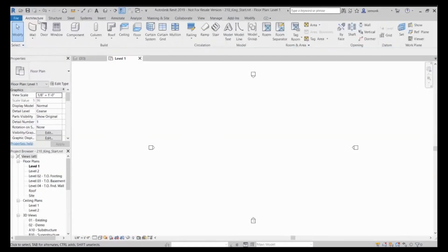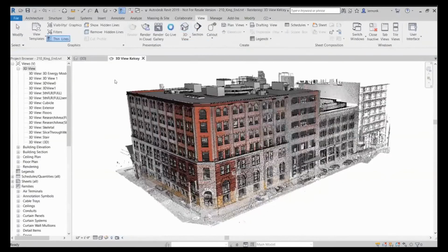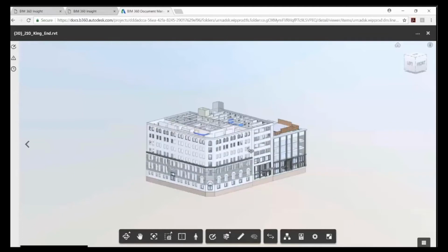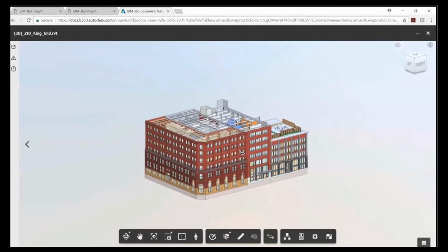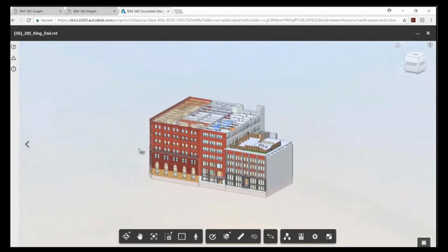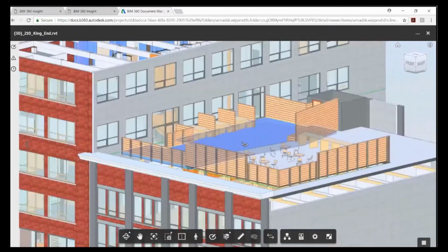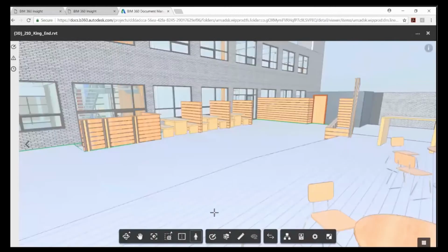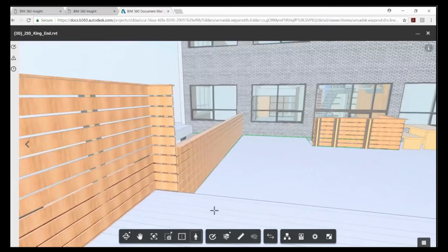And once you have done in Recap, you are able to link that data into Revit with an insert link process and use this data as the base of your design development. And this example shows the completed 3D model that is based off the point cloud data. You can see the model has been developed for structural accuracy, and of course, materials have been considered. With this level of detail and accuracy, you will be able to explore and understand the building information model in detail and feel comfortable with an accurate as-built model handoff.